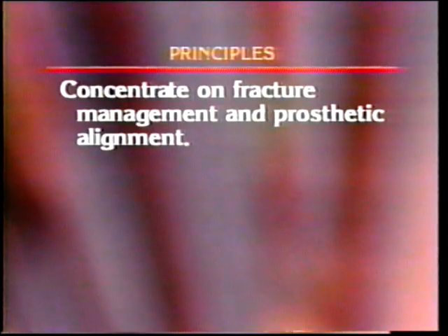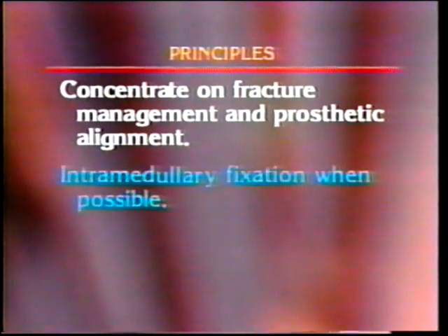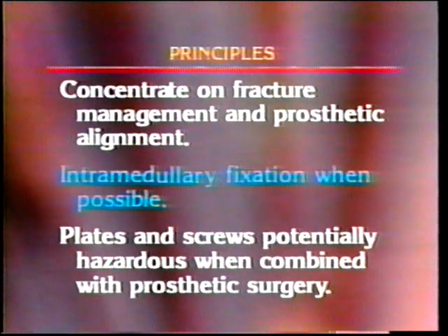So the principles then are to concentrate on fracture management and prosthetic alignment. We feel that intramedullary fixation when possible, therefore a long stem prosthesis. Plates and screws are potentially hazardous when combined with prosthetic surgery, for indeed even with new superalloys, if in placing a plate you hit the prosthetic stem with your drill in trying to put a screw in it, you'll get a tremendous notch fatigue problem and the prosthesis can break.